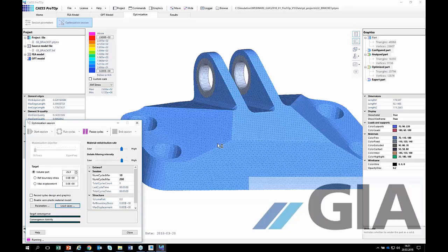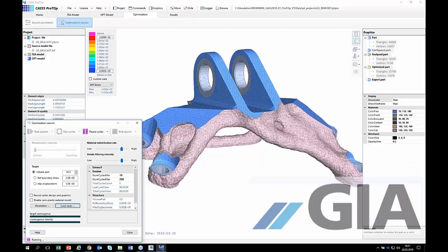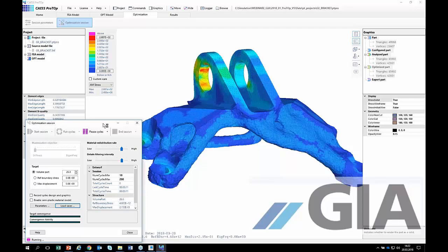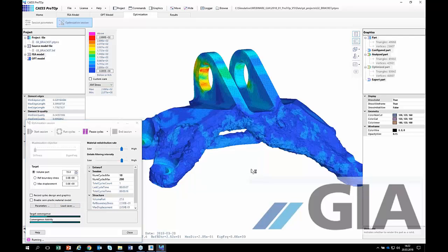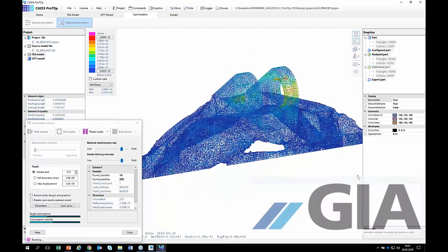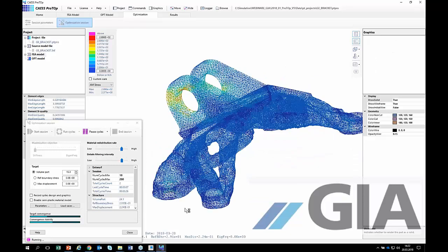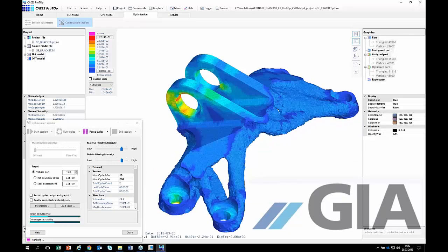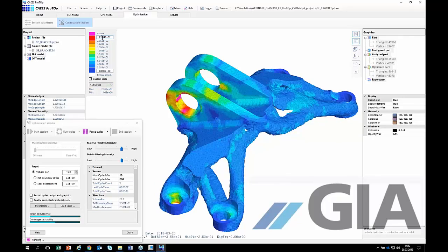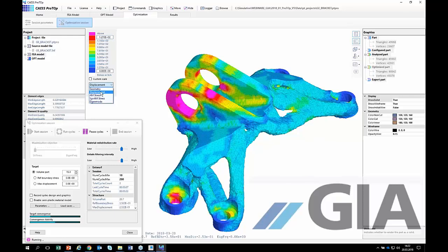So the first step will take maybe 20 seconds, and now we have a much denser mesh, and with that mesh we really can go close to the limits, maybe down to 15%, and see a very interesting organic structure of that component. So we see right now it's coming down. We're going for our stresses. We're changing the stress levels here, or we can see our displacements.